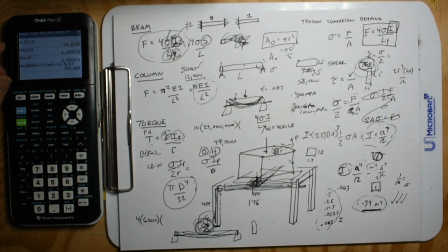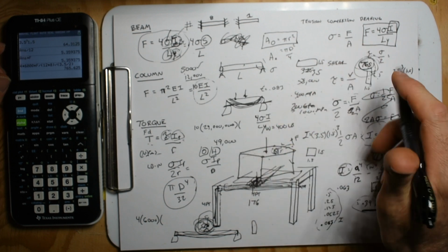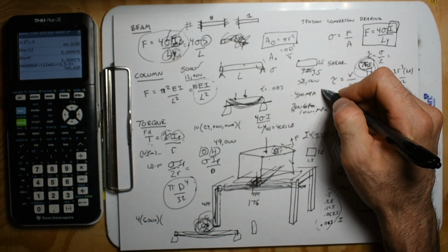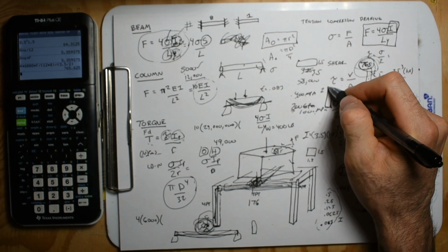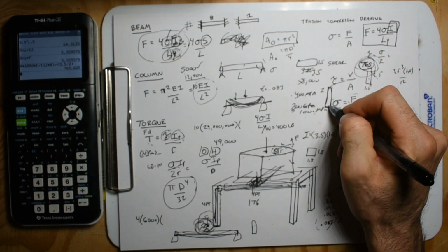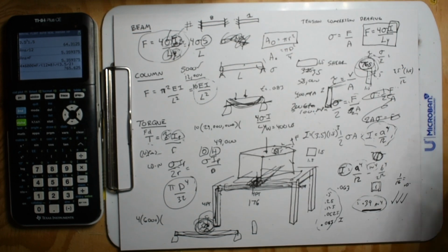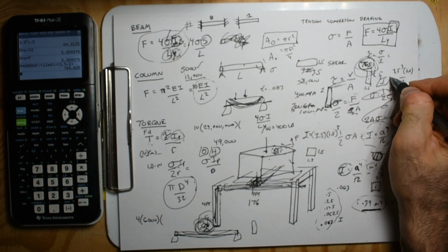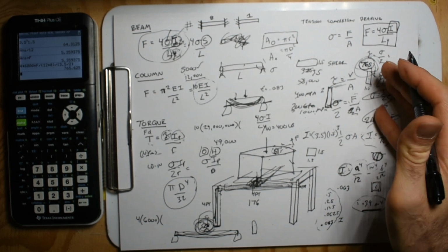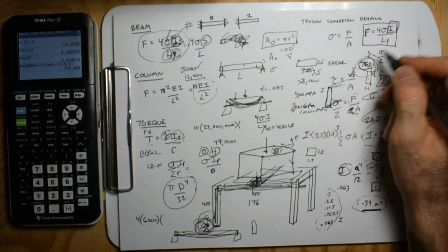So do a 2x4 this way and that way, and memorize those numbers so you have that reference. If you have something bigger than a 2x4, like a 2x8, and you have it vertical like you're using it for an actual, I forget the terms, joist or girder or whatever, hell yeah, your I value, that shape number, is going to be way bigger. And that influences how much force you could probably put in the middle.